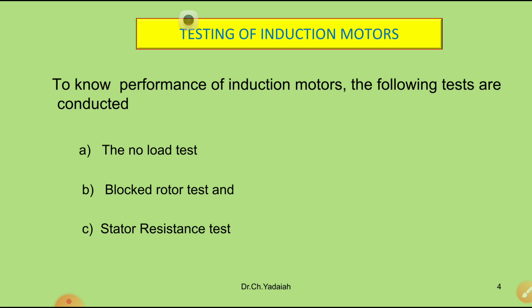You have performed the no load test and short circuit test on a single phase transformer. By conducting those tests in previous classes, you found the X0, R0 and Z01 referred to the primary side.